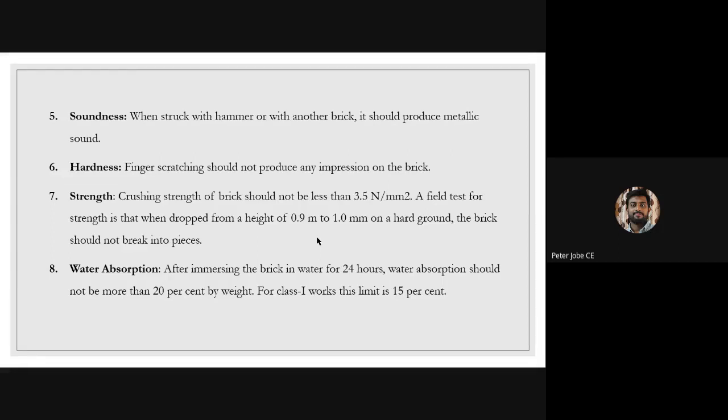And the next property is hardness. If we scratch the surface of the brick with our fingernails, it should not produce an impression on the brick. If you start scratching the surface of the brick and it produces an impression, then that brick is not of good quality. So this is the hardness property. And the